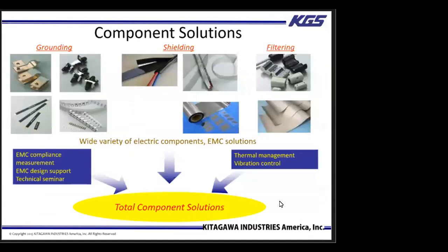There are also other component solutions as well. So other than the filtering, there are also shielding and grounding techniques that can be considered depending on your applications and where the noise problem is. And maybe it needs to be a combined solution of these three to help to reduce the EMI noise.